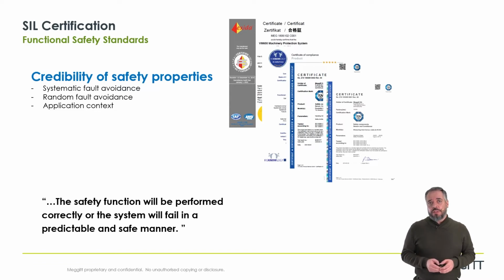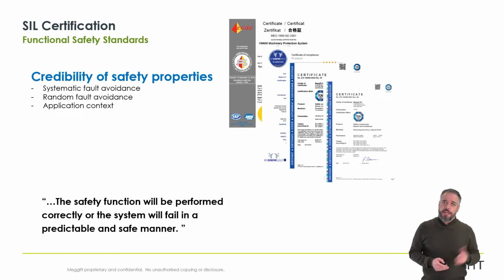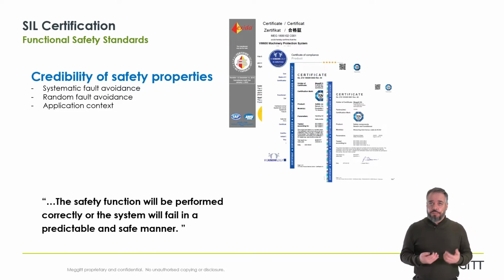But sometimes you need some more formalism, either because the reputability of the device is not established or because there are stronger SIL requirements, technical or legal, behind. In that case, you will benefit from choosing a certified product, because it will mean that the safety properties of the element were properly validated. It also reassures you that your supplier has a good quality system and that you will have access to complete safety data that is crucial to construct a properly designed safety instrumented system.